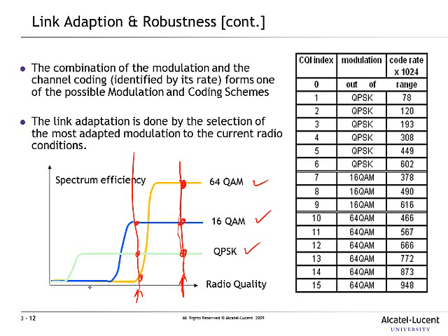And when the radio link quality is poor, which corresponds to somewhere here, and again, if you were to draw a vertical line, you see that QPSK gives you the best performance in this case. Okay, and this is something that is performed in LTE, and it is referred to as link adaptation. Okay, we adapt to the channel quality or adapt to the link quality.